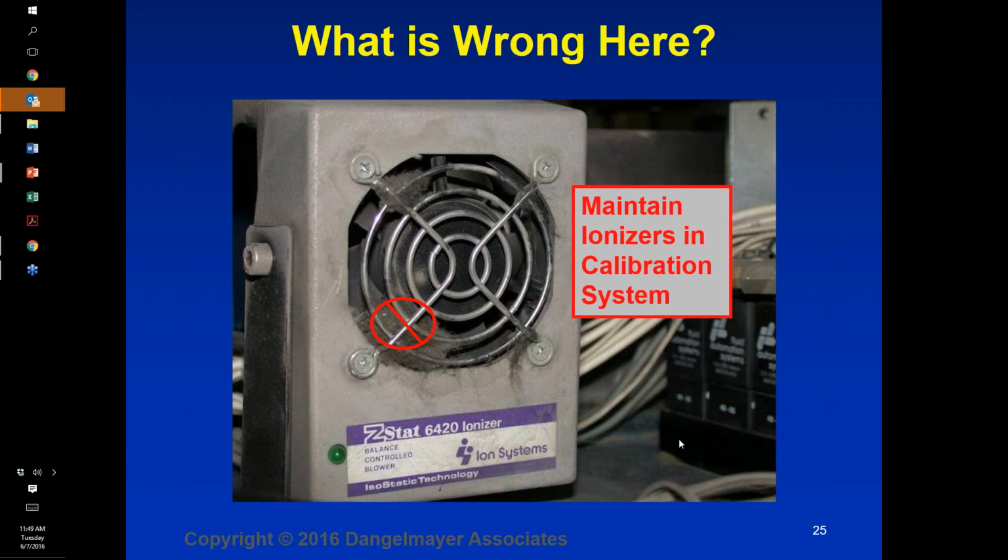But most of the ionizers that are used, at least the ones that are produced in the U.S., the ozone is measured from them, and it's at very low levels, in the 5 parts per billion range, which is much lower than the OSHA requirement of less than 200 parts per billion. So ionizers produce very low levels of ozone. There are ionizers that I've seen over the years that do produce noticeable amounts of ozone. I wouldn't use those ionizers, but none of the ionizers that I know of produced in the U.S. have significant levels of ozone.